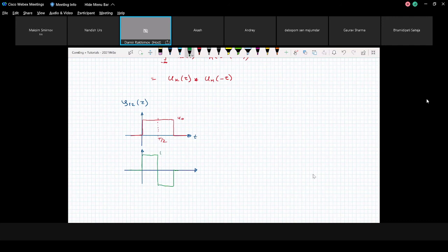And amplitude Q0. So now, once again, when we take our signal and select positive delays, we shift it to the left. When we choose negative delays, we shift it to the right. It helps us to find the proper cross-correlation function. And my first question: what's the value of the cross-correlation, so-called phi 1,2 of tau, for zero delay?